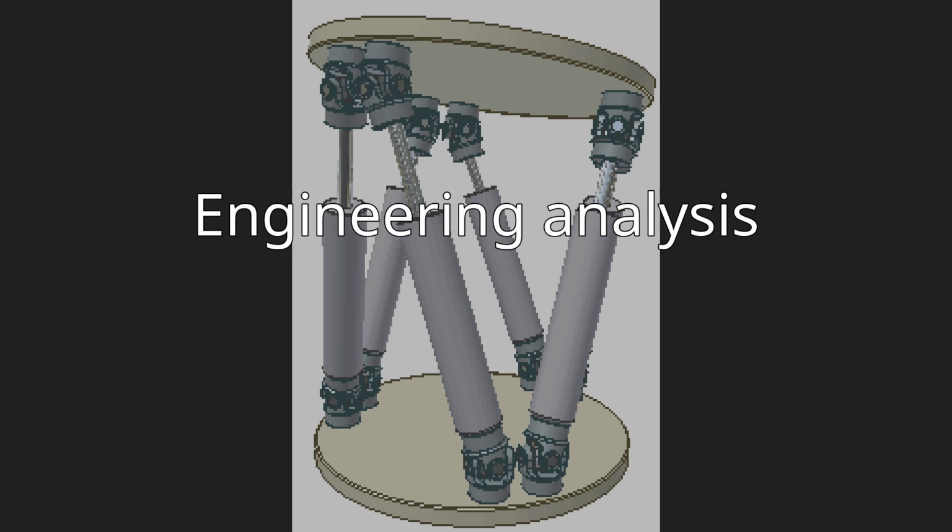By connecting a simulated cockpit with visual screen to a real flight control system in a laboratory, integrating the pilot with the electrical, mechanical, and hydraulic components that exist on the real aircraft, a complete system evaluation can be conducted prior to initial flight testing. This type of testing allows the simulation of seeded faults, i.e., an intentional hydraulic leak.